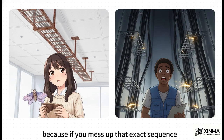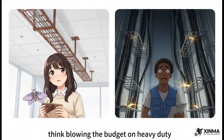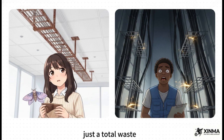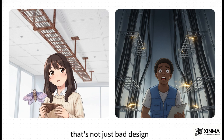Because if you mess up that exact sequence, your system is inevitably going to suffer from one of 2 project-killing extremes. On one hand, you might overspecify where it's completely unneeded. Think blowing the budget on heavy-duty marine-grade trays for a standard office drop ceiling. Just a total waste. Or even worse, it underperforms where it's actually needed. Imagine using light-duty trays for heavy main risers. That's not just bad design, that is a serious physical hazard and a guaranteed code violation.